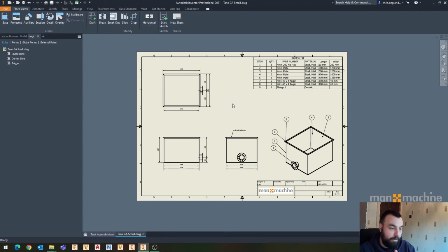It starts with the basics. We can get from creating a simple flange and doing simple things like that to creating models that are parametrically drivable within our libraries. It's always going to be handy to just pick up a flange, know that it's got several sizes in it, change one parameter, boom, it's the right size, and use it in my model. It's going to save you having to either draw flanges or draw 7 of them and pick the right one.